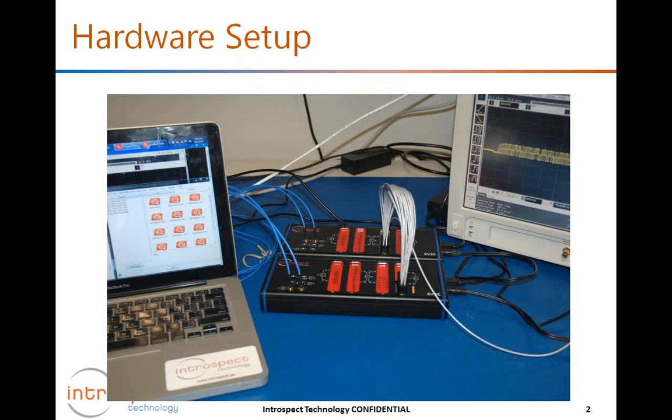So the hardware setup for today's demo is similar to previous demos. The generator is shown on the top part of the image here, and right next to it is the analyzer instrument. Both tools are able to produce 4 lanes, in the case of the generator, of C-PHY compliant signals, and in the case of the analyzer, to receive 4 lanes of C-PHY compliant signals. That's the connection shown here with the high density, high performance MXP cables. The generator also features extra replica channels that can be displayed on the scope.